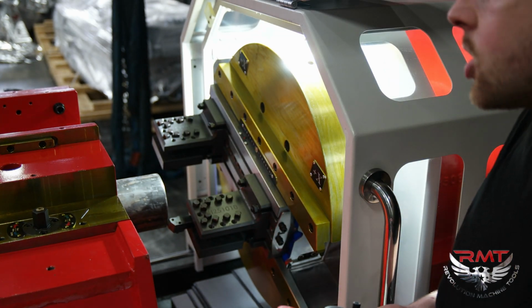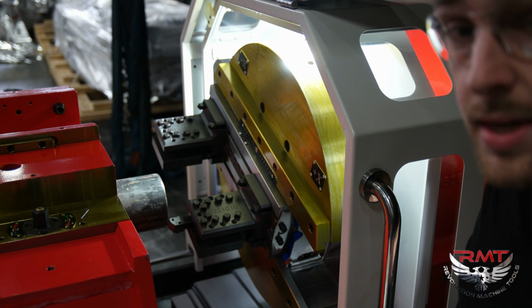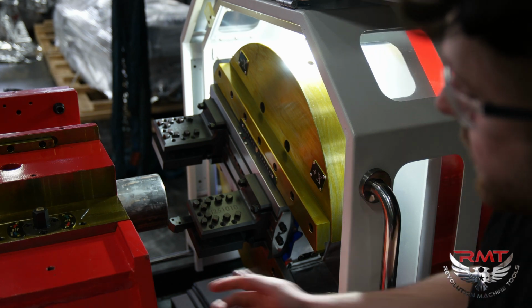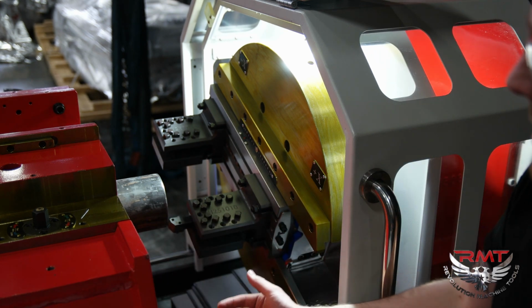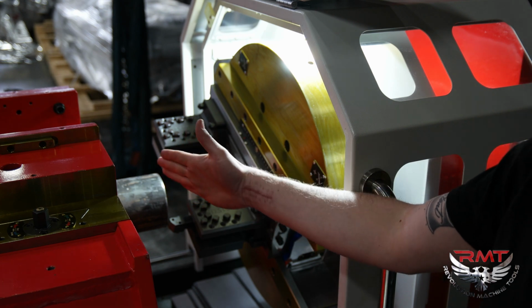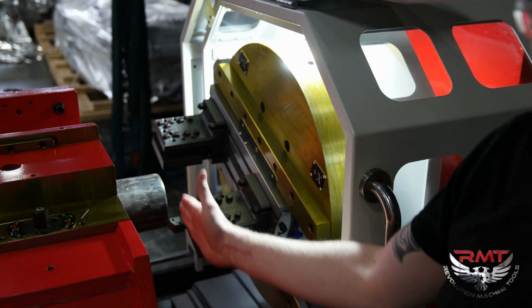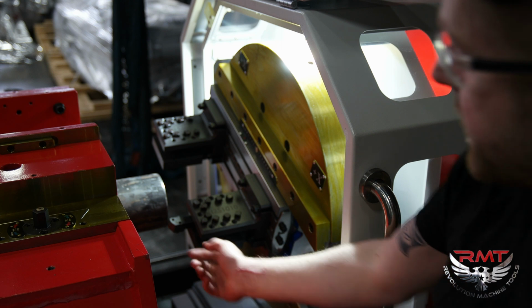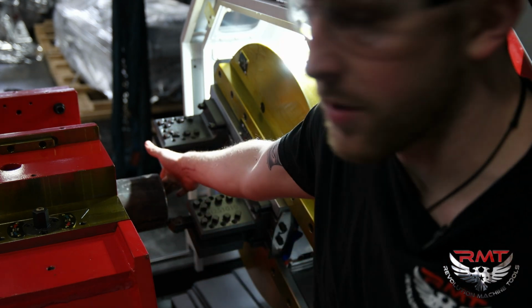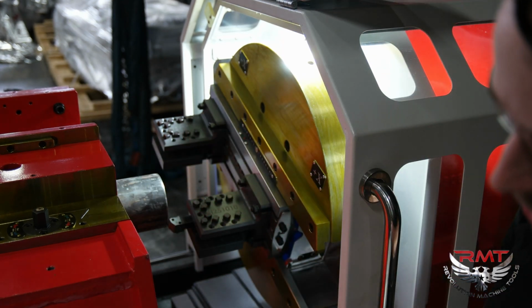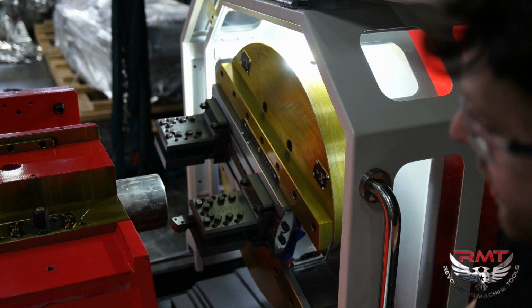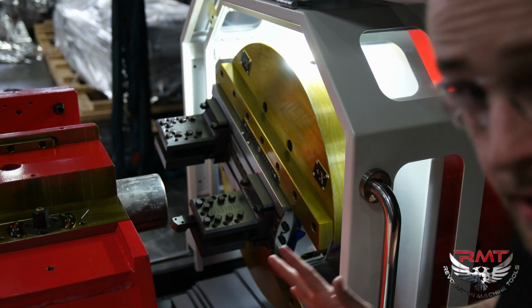surface of that carbide insert on that material. Now again, I want to stay a little bit away from that face because this is not necessarily squared to the machine yet. So if I start too close, it might come over here and hit really, really hard. So I'm just going to make sure that I'm amply away, about a finger or so.